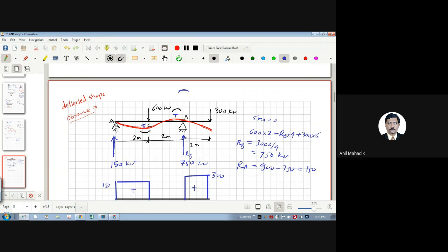So you can understand that the bending moment here will be at the bottom, and at the top there will be tension here also, it is a cantilever. So the bending moment diagram will be somewhere in this zone at the bottom, and in this zone at the top. That is our judgment by common sense by looking at the deflected shape. So from which region does this point appear? This is the point of contraflexure where the bending moment is 0.